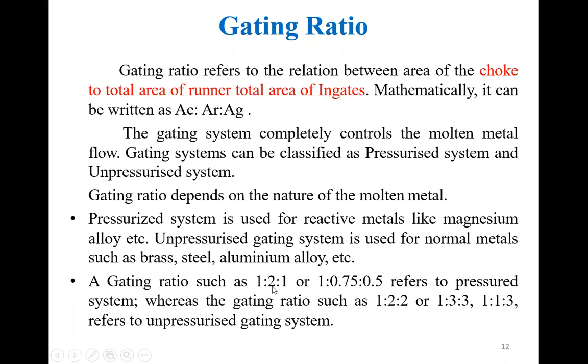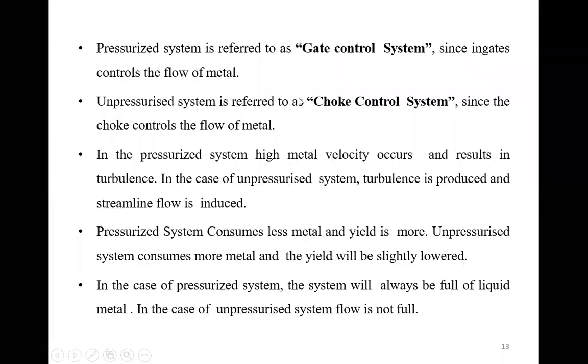So this explains that though you have a larger amount of molten metal in the runner, only a medium amount of molten metal is carried over to the gate, right, friends? So the molten metal is totally controlled by the gate system only. Though you have more molten metal in the runner, the total flow is controlled by the gate system.